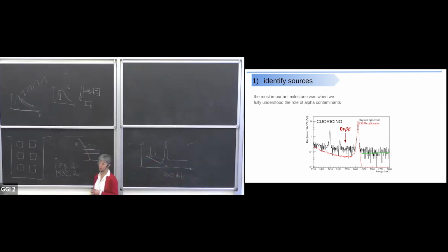In semiconductor technology, you are not able to distinguish a gamma from an electron, because a gamma interacts on an electron. The only point is what I told you in the first lecture, maybe, that a photon generally interacts in a different position inside your detector. Therefore, the signal formation, especially the charge collection, is sensitive to the position where the first ionization was produced.